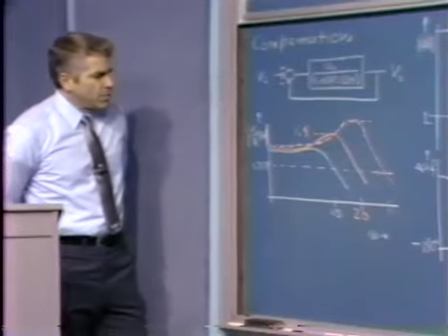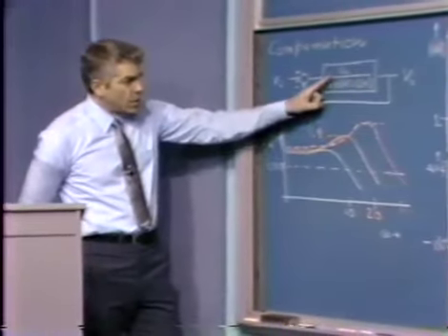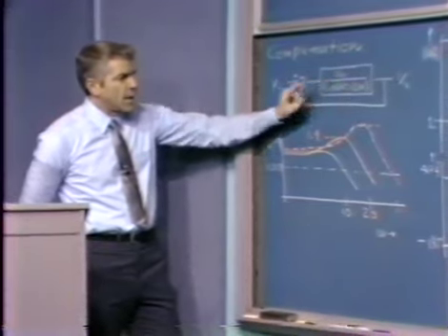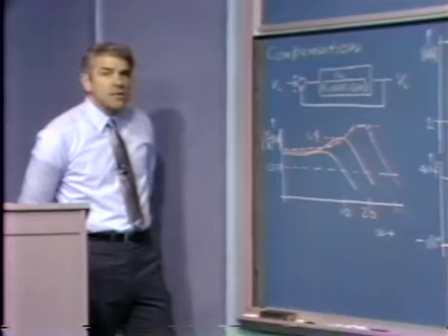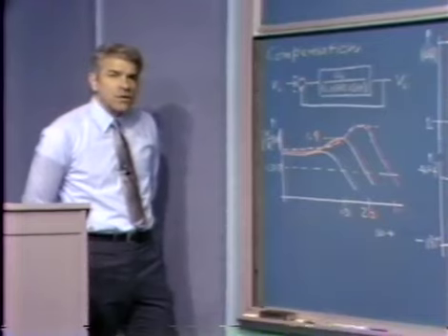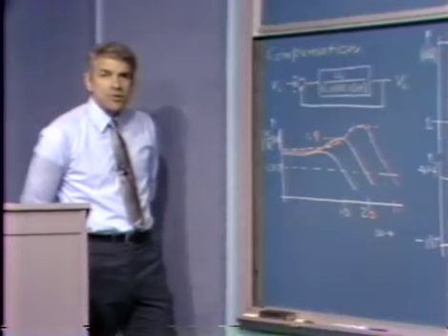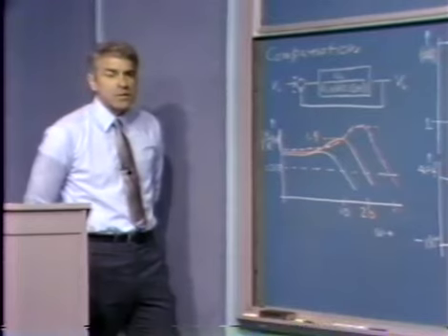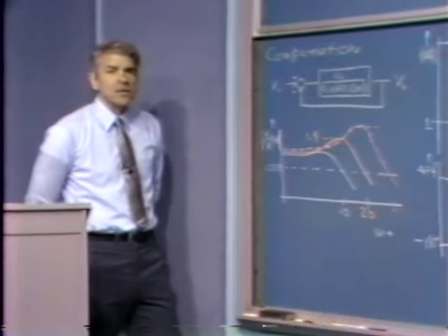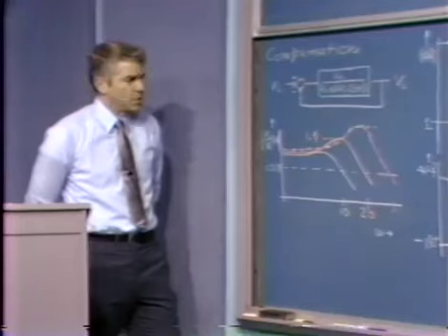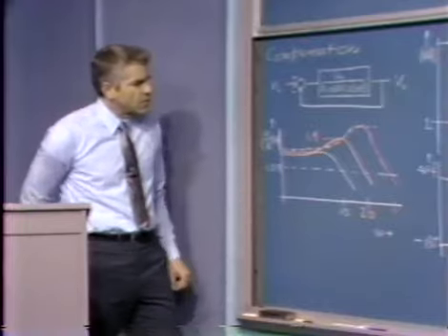As we go to progressively larger values for A naught, the system again becomes progressively less stable. The relative stability of the system drops. And that corresponds very nicely to what we've seen, for example, in a root locus development, where we saw that as we increase A naught in a two-pole system, the damping ratio of the dominant complex conjugate pole pair, the only complex conjugate pole pair for that two-pole system, gets progressively smaller. So we'd expect this behavior, that the system becomes progressively less stable for larger values of A0 in the two-pole system. And our Nichols construction confirms that.